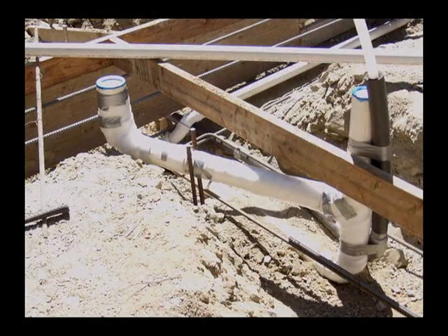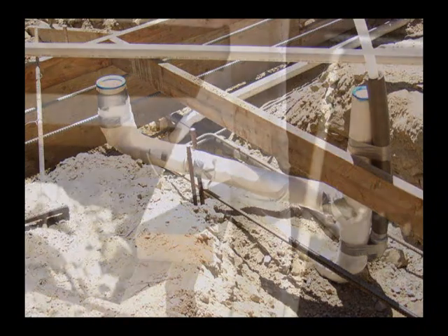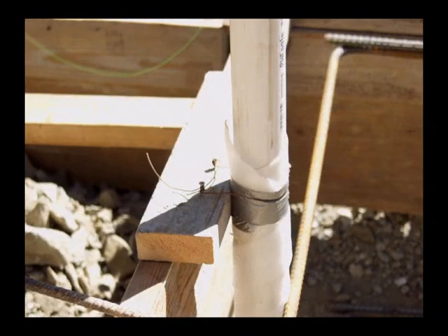Again, you can see we've got the insulation on the water lines as it passes through the concrete in the right of the frame here, and then the sewage lines are wrapped in a felt and taped. And again, here you can see this is a vent pipe coming out of the concrete. We have it wrapped in this felt and taped and then wired off to a block holding it in position so it doesn't move during the pour.